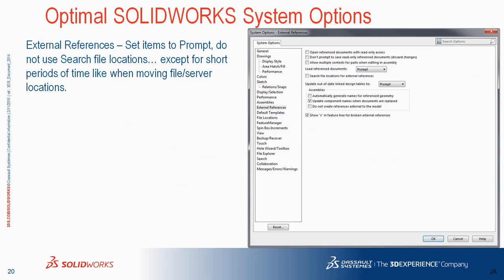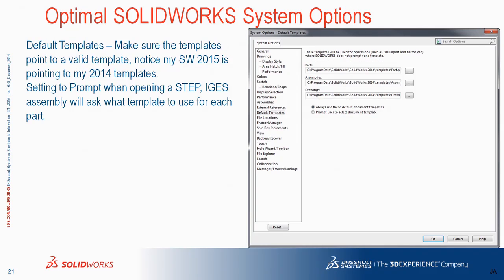Yes. Were you in our last presentation? Okay, because we did cover that. Antivirus scanning does affect SOLIDWORKS performance. So turning off scanning for SOLIDWORKS files as it goes back and forth across the network, on both the server and the client, can improve performance. I believe the number there was somewhere in the 10 to 15% range. And speed things up. You just got to make sure that you're scanning for everything coming into that network so that you catch viruses at the right spot. And make sure that you're only excluding SOLIDWORKS files, you're not turning off antivirus. Good? All right. Very good.